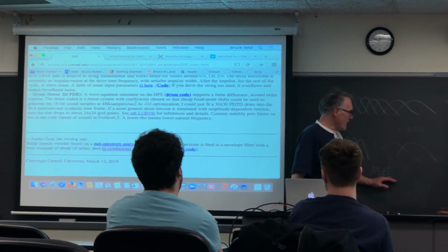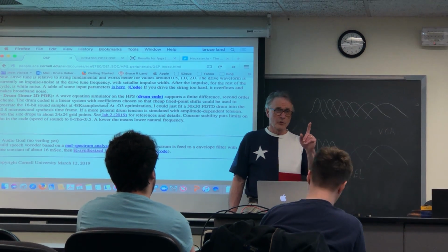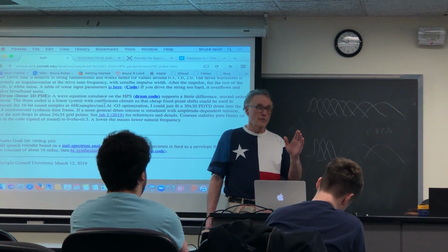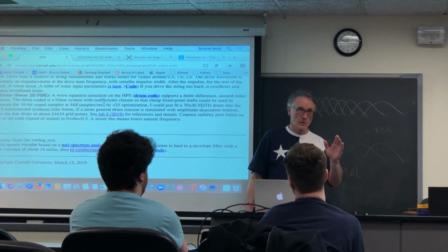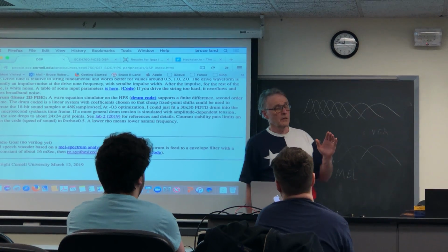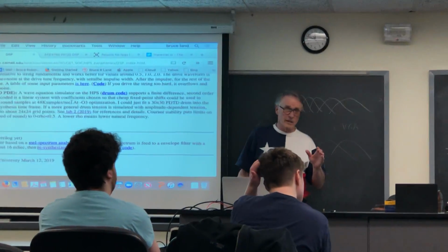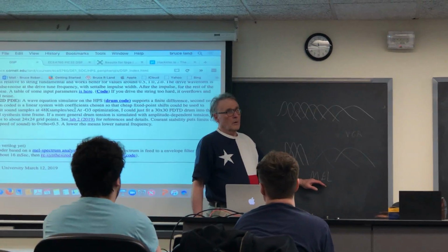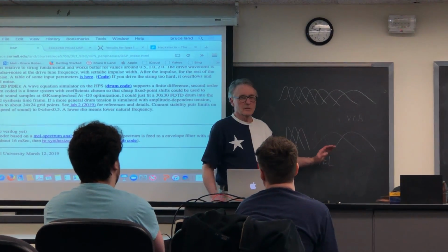Also, a Mel frequency bank could be the first step for input to a speech recognition algorithm, or for a speaker recognition algorithm. Because the first step in doing speaker recognition is to take the Mel spectrum and then do the FFT of the spectral components.